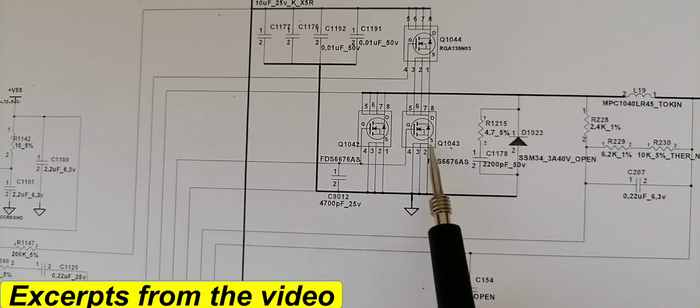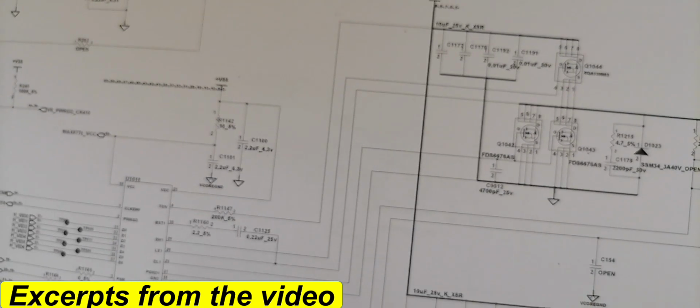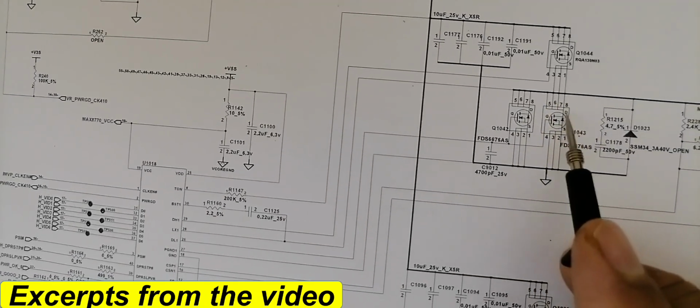So this is the source. Do you see S? And here the 4th pin is gate. The gate is always connected to an IC, a control IC. So 3 pins for source, the 4th pin is for gate, and the other 4 pins are for drain.